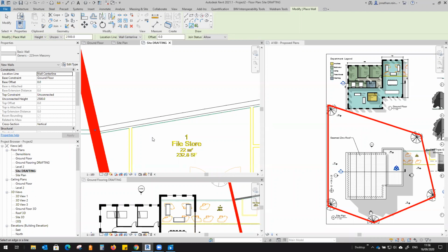So it definitely has to be elsewhere. You might have to find them. BIM Object again is another great library. As you said, alternatively, I personally would probably use the curtain wall tool just because I think it's quite dynamic in terms of what you can do with it. I suppose it depends, are you outputting that onto a sheet for a window schedule, which can also be done even with a curtain wall. So yeah, you can do it both ways, to download or create from a curtain wall. Yeah, perfect.